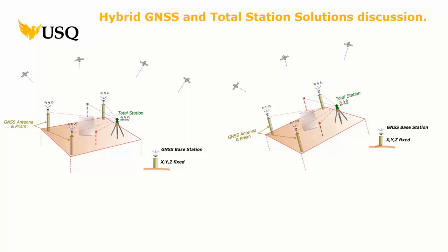Now, if you go back to your close range photogrammetry, a topic you'll never forget, if you remember, when you had a bunch, or laser scanning, a bunch of points here, right? And they're like moved around. You've got a bunch of points here that are less moved around, so they're known, control, or thousands of points, right? You normally do between the two what's termed a Helmert transformation. It's like a fancy affine transformation, more than 6 parameters, right? You can go through the mathematics here and work it out. So that's what's going to happen. Is when you get tilting it, you're going to do normally what will be a Helmert transformation.